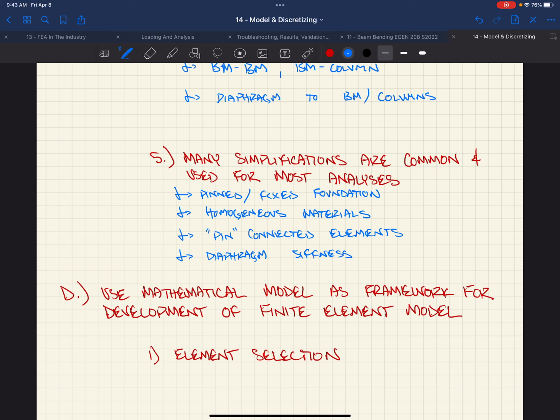On the inverse of this, though, right? Now you can design the walls on the outside for 0.375 WL, which sucks sometimes, because often your exterior walls are the best shear walls you have, and the interior, if you do add another one in the middle for aspect ratio or something. And then that also assumes a pure connectivity across there, right? It's saying that it's not going to crack, the stiffness is going to stay the same. If it does, it's wood, it's probably going to crack, it's probably going to displace a little bit. The minute it displaces some, this is going to go up, right? So I might argue you might design some of these interior ones for this value and the exterior ones for the 0.5.